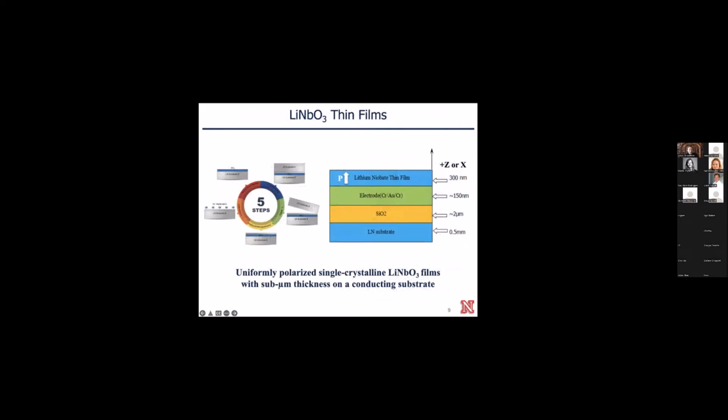Our studies actually follow up on this initial finding. In our project, we used the ultra-thin crystals or thin films of Z-cut lithium niobate, which were prepared by the ion slicing method on the platinized substrate. In the as-prepared film, the polarization points away from the bottom electrode, and it's typically a single domain state. So there are no domains and no domain walls.